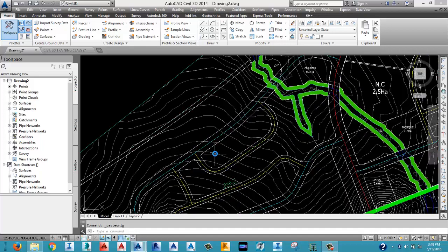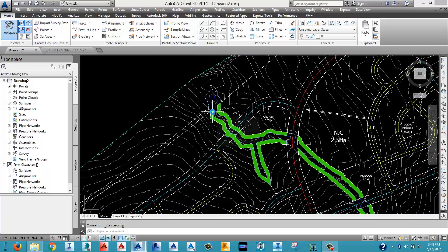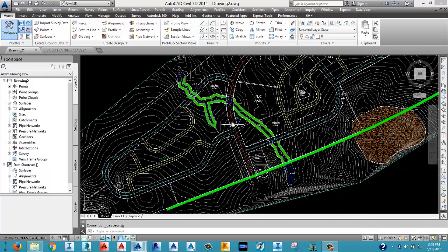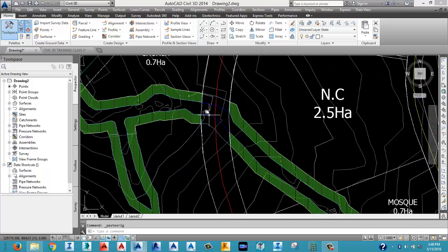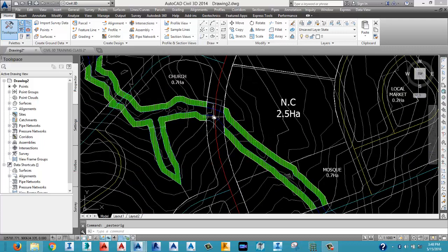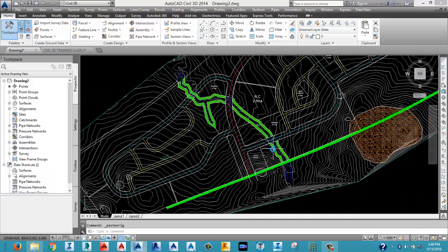Now you can see the planner actually told us, from your survey when we were working in the design environment, we already saw that there was a depression around there. This man confirmed to us that it's true, there's a stream flow around this area. So that's just a confirmation of what they gave us. At this point you already understand that there's going to be a culvert, depending on your geological report, or a river bridge along the road. Those are the things we actually think about.